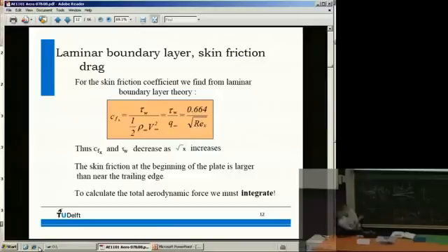Okay. This is a bit I like least. What you need to know from this really is concepts and how you would approach this. So concepts: laminar flow, turbulent flow, shear stress, friction drag, pressure drag. But because we don't really have the tools to do the nice analysis, we use the skin friction coefficient. This shear stress that we're interested in, again from laminar boundary layer theory, there is a relation relating this shear stress to Reynolds x again.